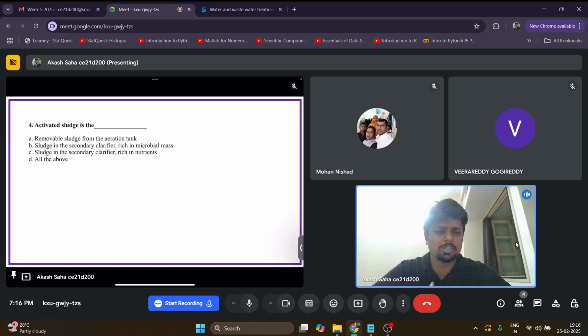Okay, so in most of the systems, the organic matter or the organic carbon acts as the electron donor, whereas in any aerobic system, we have the oxygen. So it accepts the electron, so it acts as an electron acceptor. Okay, whereas in any anoxic system, there is no oxygen present. So there the nitrate or sulfate acts as an electron acceptor. So that's what I was telling.